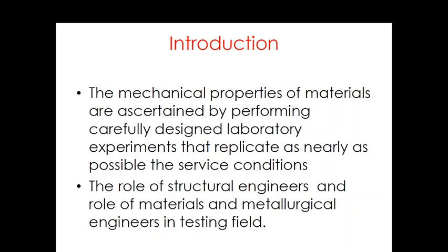The mechanical behavior of a material reflects the relationship between its response or deformation to an applied load or force. The key mechanical design properties are stiffness, tensile strength, yield strength, hardness, ductility, and toughness. The mechanical properties of materials are determined by performing carefully designed laboratory experiments that replicate as nearly as possible the same service conditions.